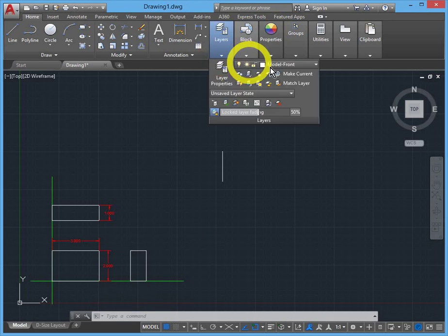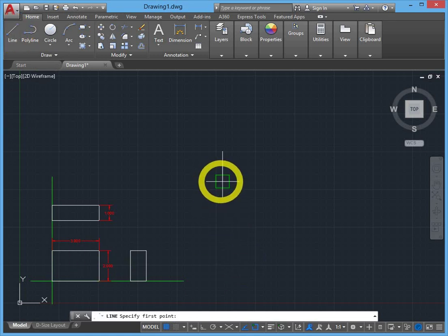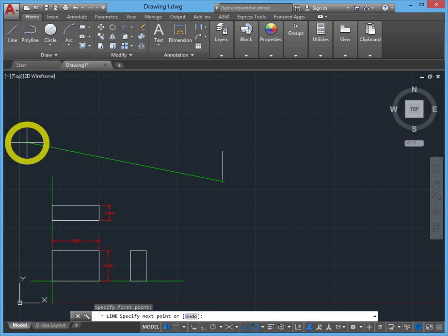The next thing I'm going to do is switch over to a construction line layer, and I need to go ahead and lay in my vanishing points. So I'm going to use this edge as my guide for that. I'm going to get the line tool, interactive method. I'm clicking here. You'll notice I'm on the lower end point of that line segment. I'm going to left click and release, and I'm dragging off at some random angle.